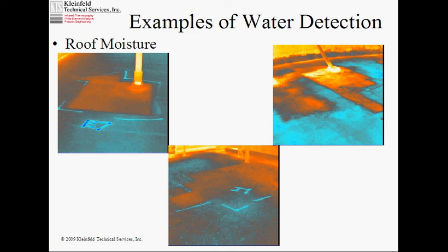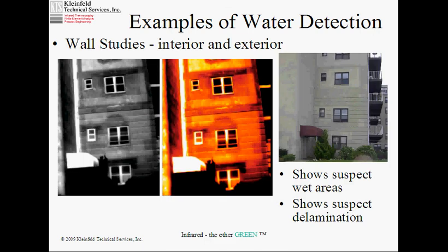So this is a transient, but one driven by natural conditions rather than one that the thermographer applies to the system. And you can see where the warm areas are marked. The E7 and I1 and so on is the image numbers, so that when I get back to the office I can say, okay, that image is there on the roof, and you can come back in daylight, or if you have a good flash on the camera, you can take a picture,